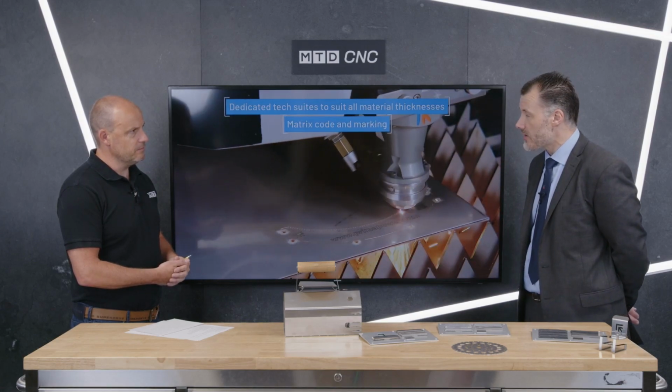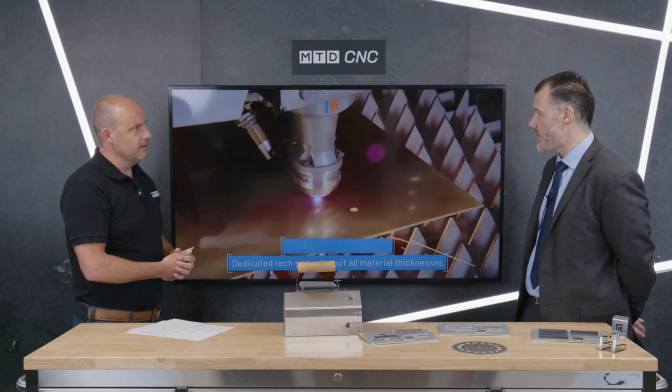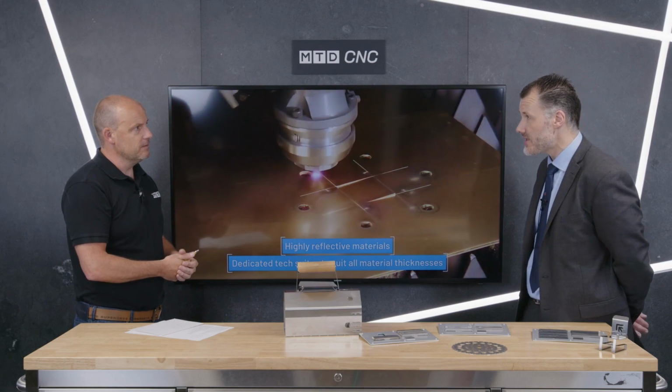So we have like the Smart Cut. The Smart Cut will basically optimize material cutting paths so that we don't have dead time in the process, so it can pierce on the fly. Instead of going maybe like it takes absolutely the quickest, quick point to quick point, and it will also avoid collisions.